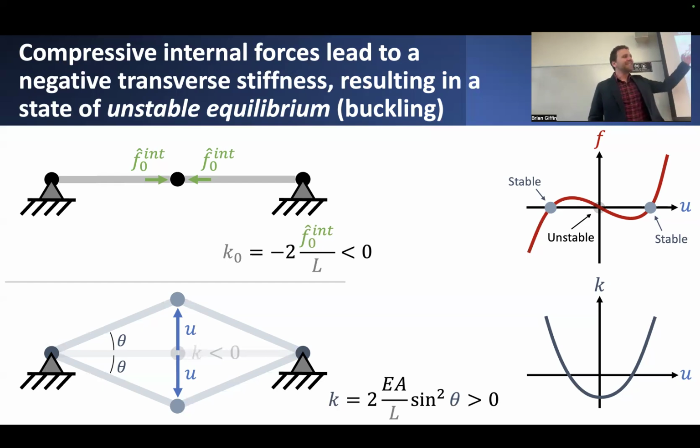Even though, let's suppose we took away that transverse load. Let's suppose we just kept this simple two-node or two-element problem as is, no transverse load, but we put in some initial compressive force. Technically speaking, if I'm not applying any transverse load, this structure is in a state of equilibrium, somewhat bizarrely. And that makes good sense.